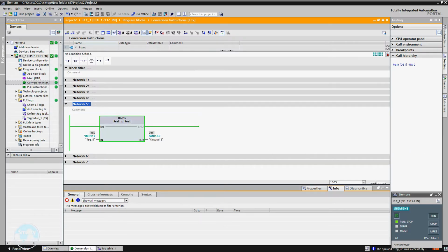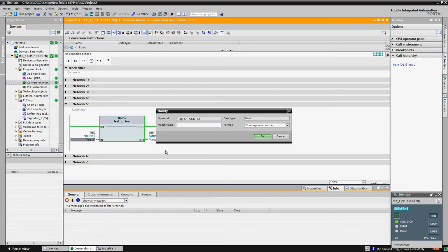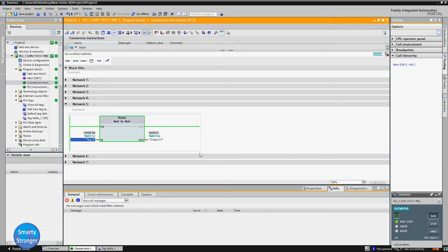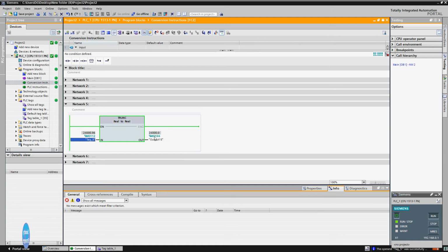Trunc. The trunc instruction is used to form an integer from the input value. The instruction selects only the integer part of the floating point number and sends this to the output pin without decimal places. You are seeing that by applying different values, it gives only the integer part. The value after the dot is vanishing. When we apply 24,000.96, the value at output is 24,000.0.